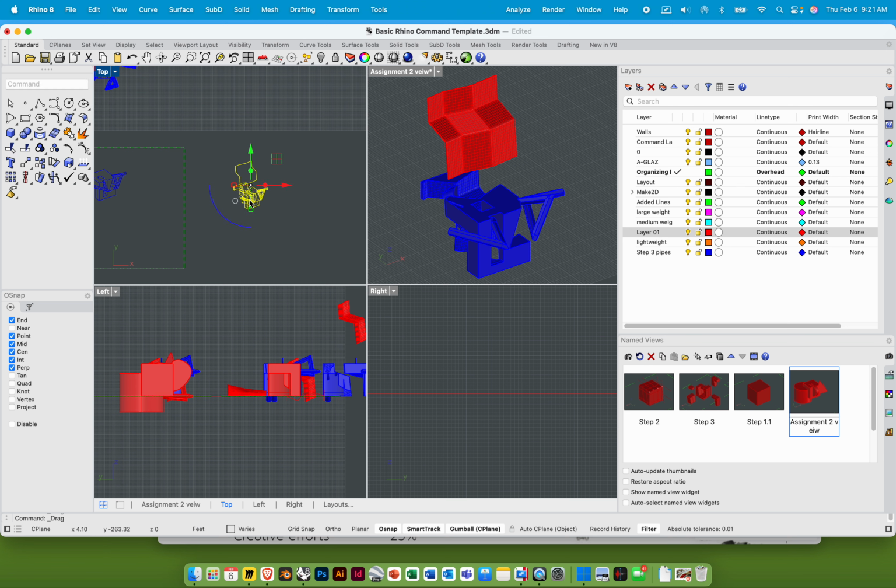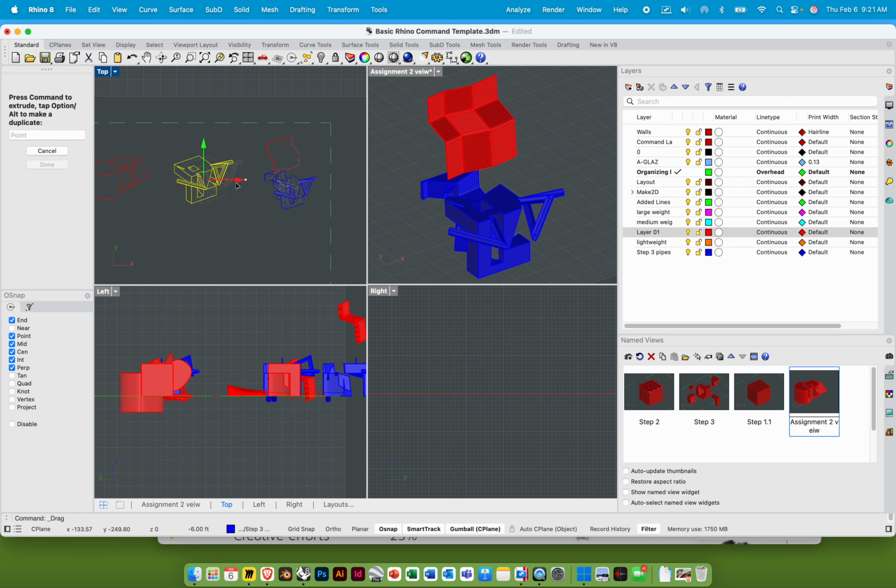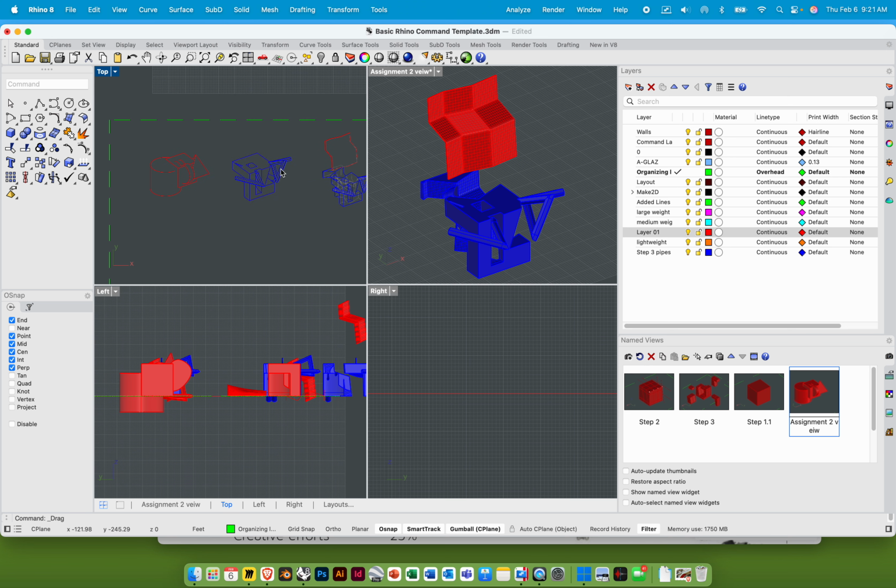Of course, holding shift and making that apparent. So we kind of have a step 1, step 2, step 3 going on. And to be fair, if you don't want to accidentally move these and have them not grouped, of course they come in grouped because we had that option to make 2D, but you can also ungroup by typing ungroup or regroup it again by typing group.